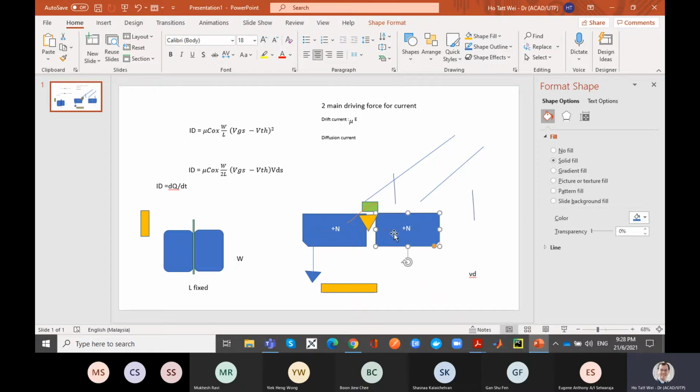This is what the modern transistor looks like. And this is why it's called a short channel, because the channel is literally very short. It's 7 nanometers nowadays. One atom is on the order of an angstrom, so you are roughly the size of 2 or 3 atoms. That's the size of your channel.